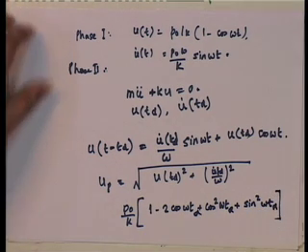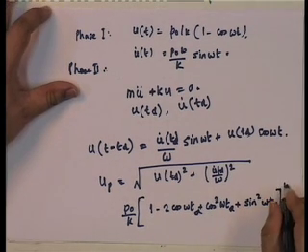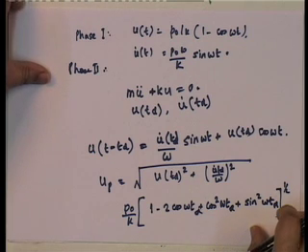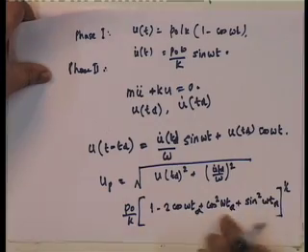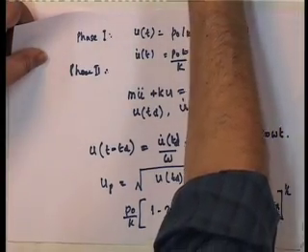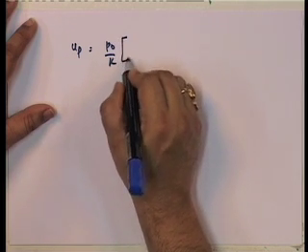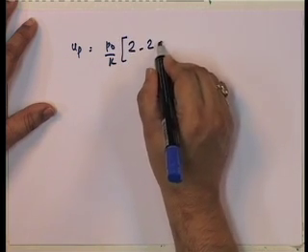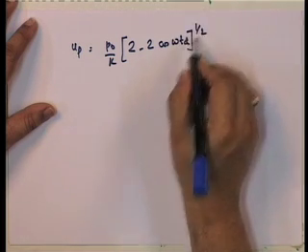That is the peak value. If I look at this, the sine squared plus cosine squared becomes 1, so it becomes 2 minus 2 cosine omega T d, under the square root. So, the peak value becomes u p equal to p naught upon k times the square root of 2 minus 2 cosine omega T d.